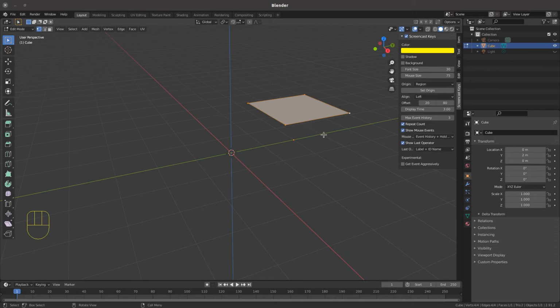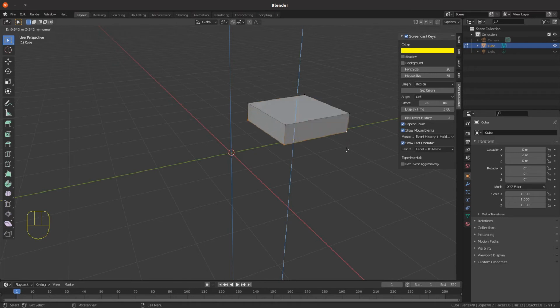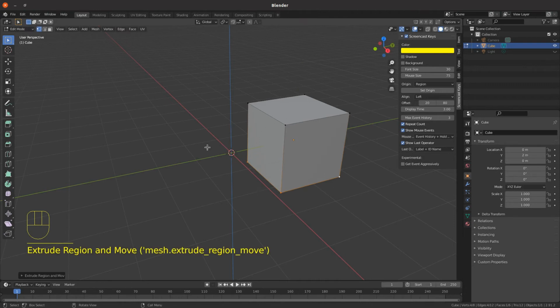With the face selected, we can now extrude that face. So we'll go extrude. Just highlight that again. Go extrude, and it's already going to extrude perpendicular to the face. So it highlights the axis along which it'll extrude with a light blue line. We can drag that down, but we're going to extrude it on the minus direction 2 meters and enter. So we've reformed the cube exactly the same as it was from that one single vertex.